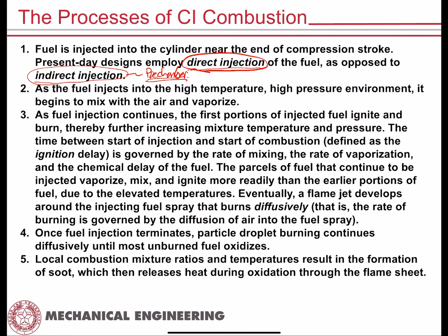Okay, so as that fuel injects into the high temperature, high pressure environment, it begins to mix with the air and vaporize. So the mixing, that's where we have these 4 processes of penetration, breakup, and atomization. And then, of course, the 4th process I have listed in the text, and that is vaporization. So you have to do these 4 processes before the chemistry can start. You can't ignite, you can't oxidize a liquid. It has to be vaporized.